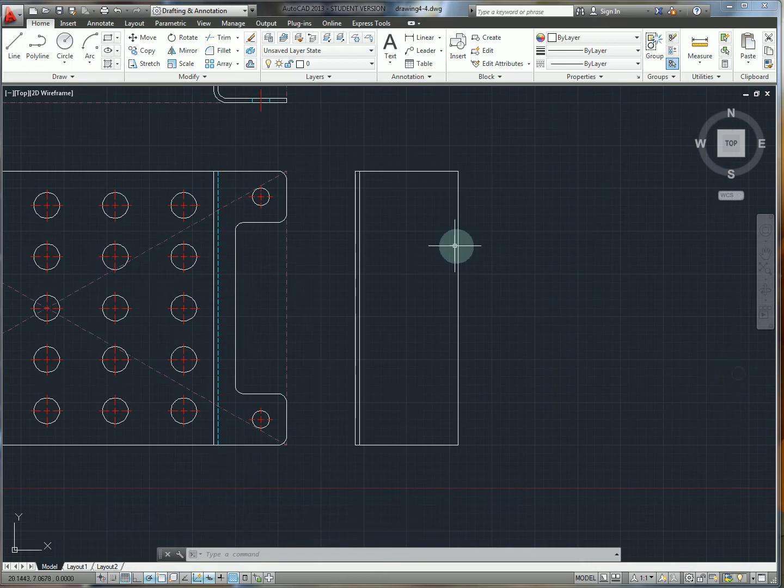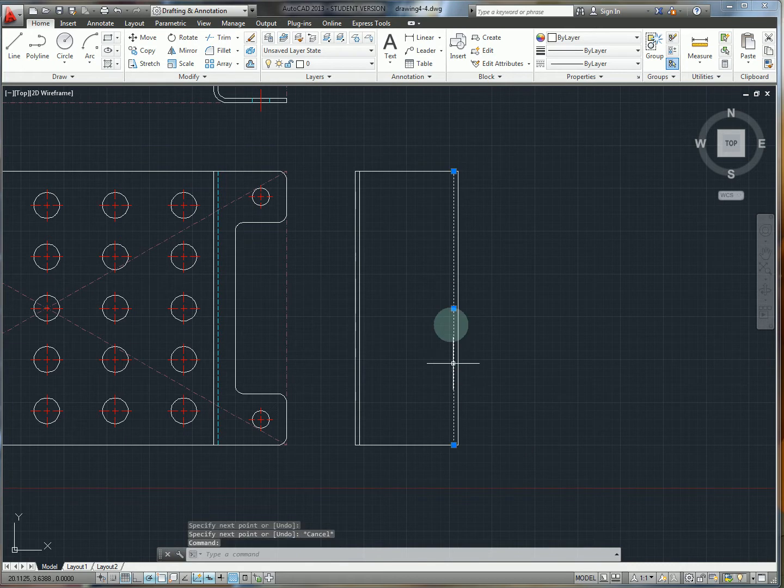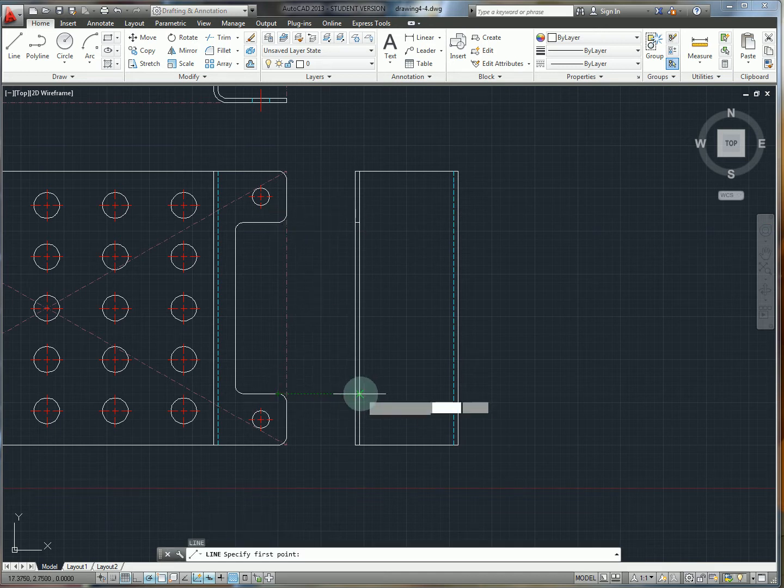We also have a hidden line that's going to be an 1/8 of an inch in here. So again, I'm going to use polar tracking and OSNAP so I can directly enter that amount. Once I've drawn this line, I can throw that on the hidden layer. And finally, I want to, again, OSNAP polar track, get these edges here propagated over. And the nice thing about this is, of course, I don't have to do any measurement. I just line up the cursor and sketch away.